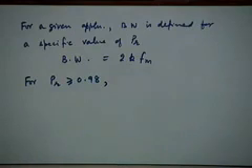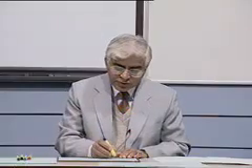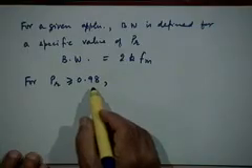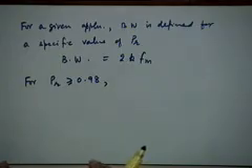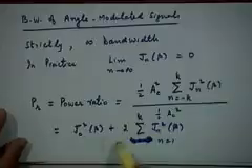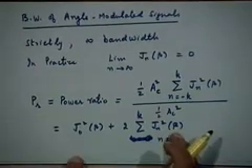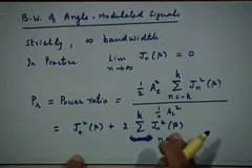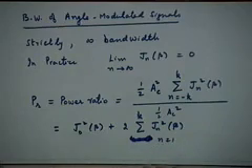Now if you look at the table of Bessel functions, a very interesting fact comes to light: if you choose PR to be greater than 0.98, the value of k that you need so that this becomes 0.98 depends on the value of β. But there is a very nice closed form. Of course it's not closed form in the mathematical sense, it's in the empirical sense.